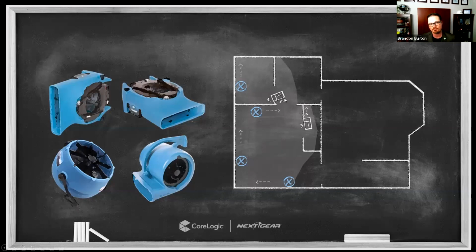And note that as I move the exhaust from this air mover, if I move in this clockwise direction, I'm continuing this flow all along the perimeter of this room, right? So that ensures that this air moves through the entire space before it jumps back out the door again. Let's start down here and again, follow from this first air mover through and around the entire space, then into the neighboring room, and then through and around the space of the neighboring room.